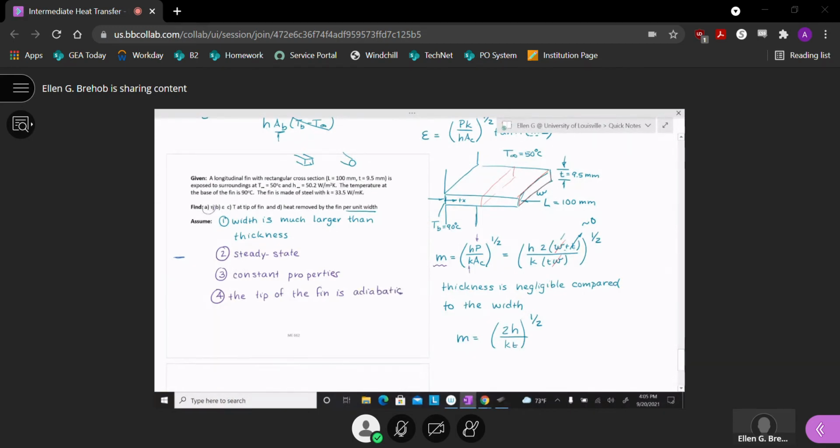We saw that table the other day, and it had different boundary conditions for the tip, but I'll tell you that adiabatic is pretty common. And so if I wasn't given any information, I'd use the adiabatic case. And then we're moving into a little bit more unusually shaped fins, and there we only have the option for the tip of the fin to be adiabatic.